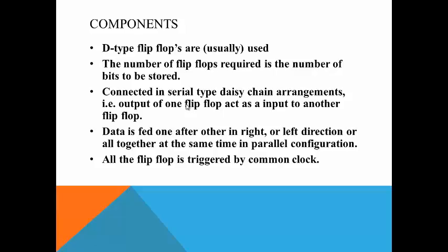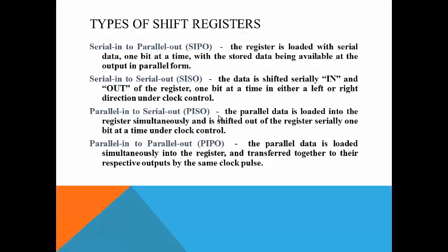That is, the output of one flip-flop will act as the input to the other flip-flop, and so on. So data is fed one after the other in the right or left direction. You can have either right input or left input, or all together at the same time in a parallel configuration. All the bits can come in parallel also. So all the flip-flops are triggered by a common clock. Okay, it is a synchronous sequential circuit. So all the flip-flops will have a common clock.